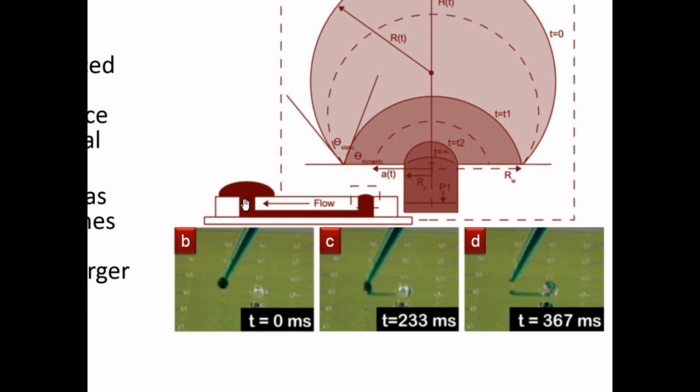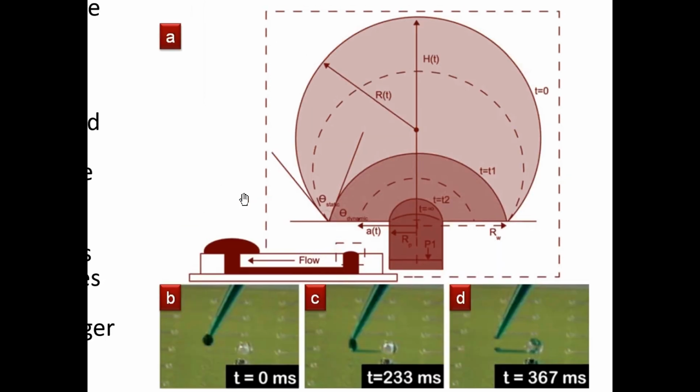Now, suppose you were to put a large drop of liquid in here, and you were to fill the channel, and then you have a smaller drop of liquid here. What would end up happening is you'd get flow going this way to this way. The reason why is actually pretty simple. Imagine two bubbles here, and the two bubbles have different radii.